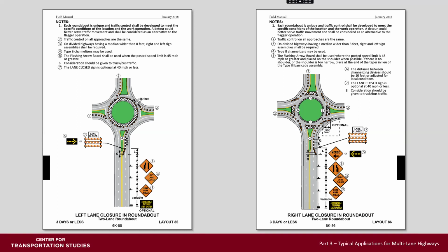Multi-lane roundabouts are often easier to control than single-lane roundabouts during maintenance operations. One lane in the roundabout may be left open and will be treated as a single-lane roundabout. Even so, it's important to remember that commercial vehicles need additional space for off-tracking of trailer tires.